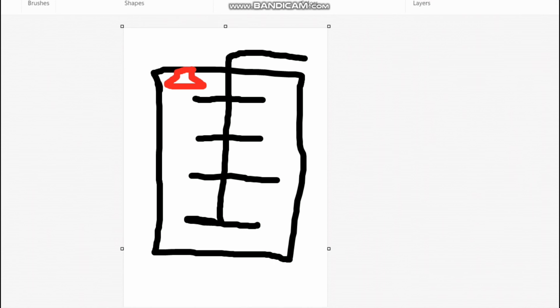So it is good engineering practice that if we have, say, 8000 CFM, meaning more than 4000 CFM, we can make an additional return air plenum. It will improve the indoor air quality and provide proper return air to the system.